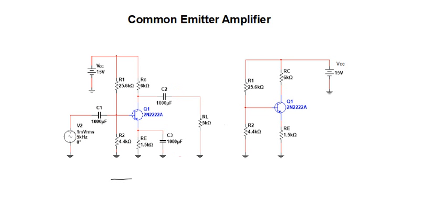Now, what an amplifier does is we input a small AC, this is just a millivolt, a small AC voltage into the base of the transistor, and it excites the transistor to the point that it carves out from this DC supply a bigger version of that AC.